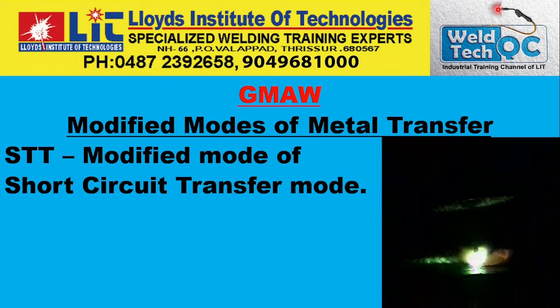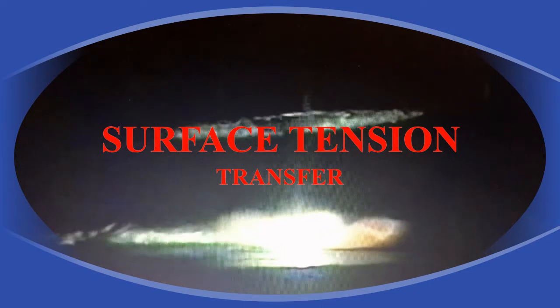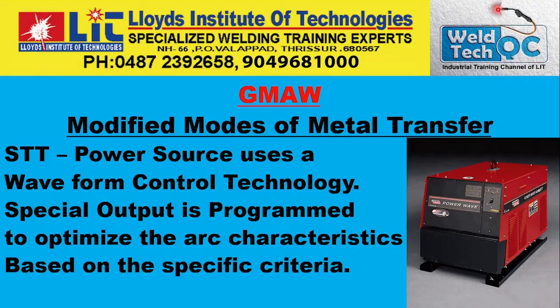We'll discuss STT. The power source uses a waveform control technology. This is applicable not only for STT but also for the pulse spray transfer. The power source, the machine, uses a waveform control technology. Special output is programmed to optimize the arc characteristics based on specific criteria.